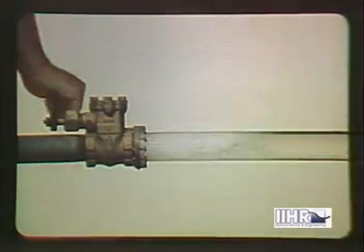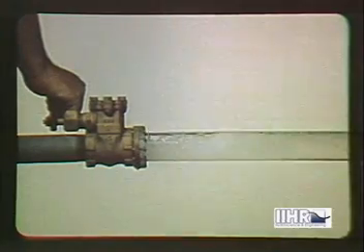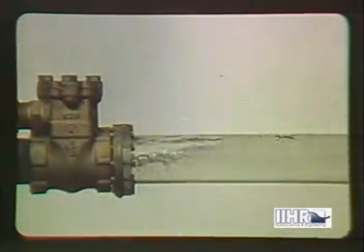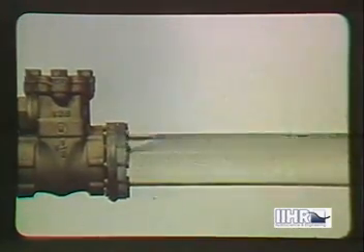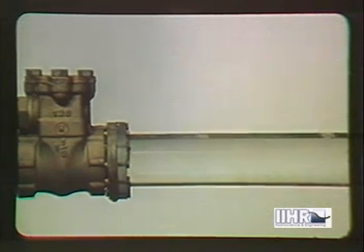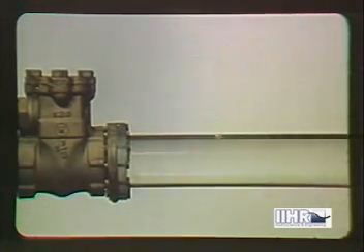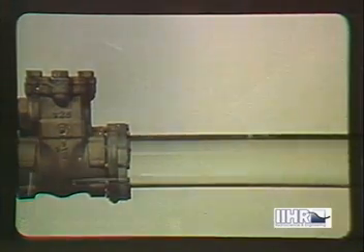Conversely, the reduction in pressure, when the wave becomes negative, can produce cavitation of the liquid, as seen here in slow motion, the initial vapor pocket thereafter collapsing against the valve and then tending to reform repeatedly. Because of the noise that is produced by the sound wave in either case, the phenomenon is very aptly called water hammer.